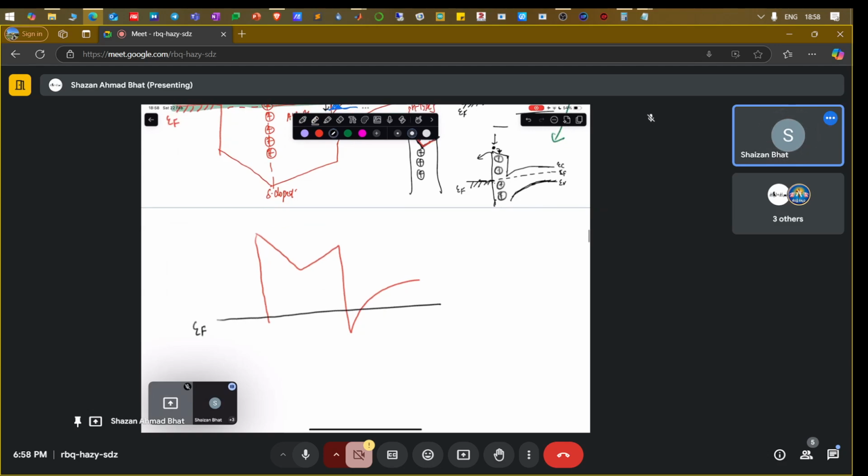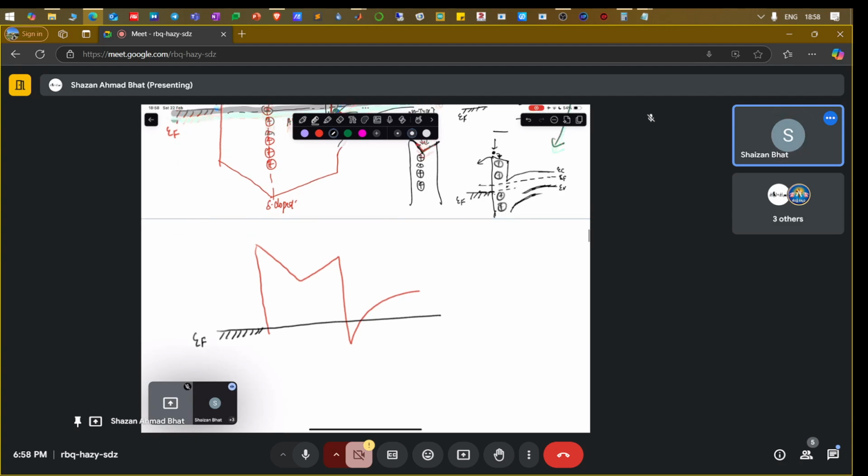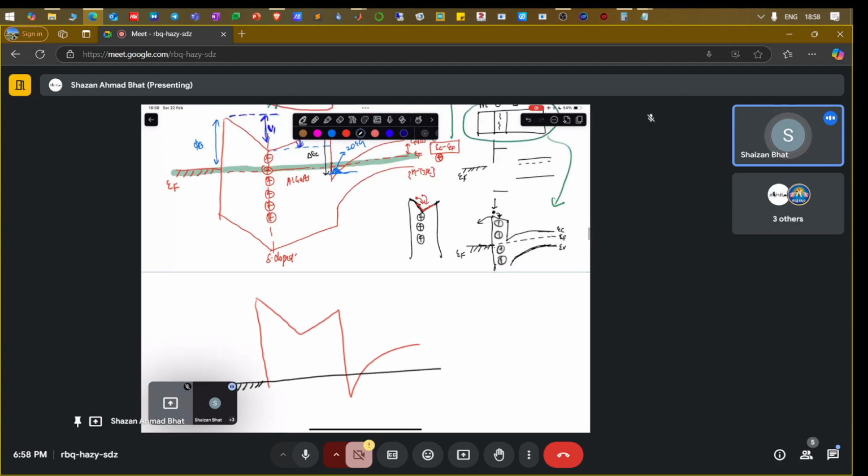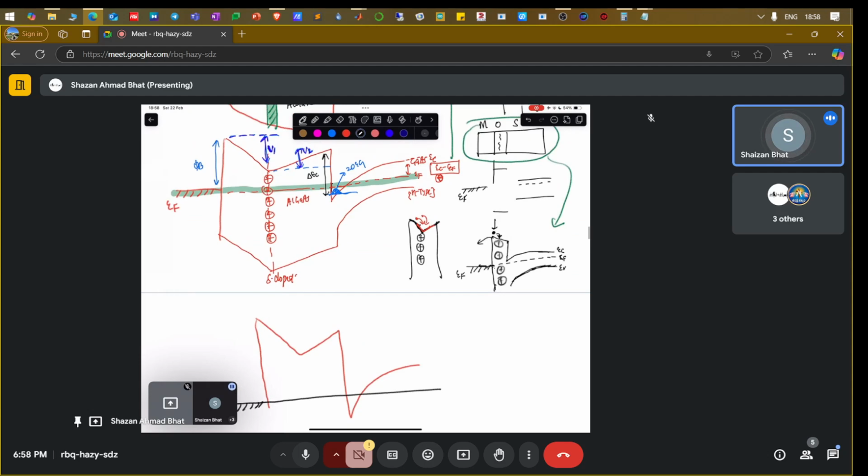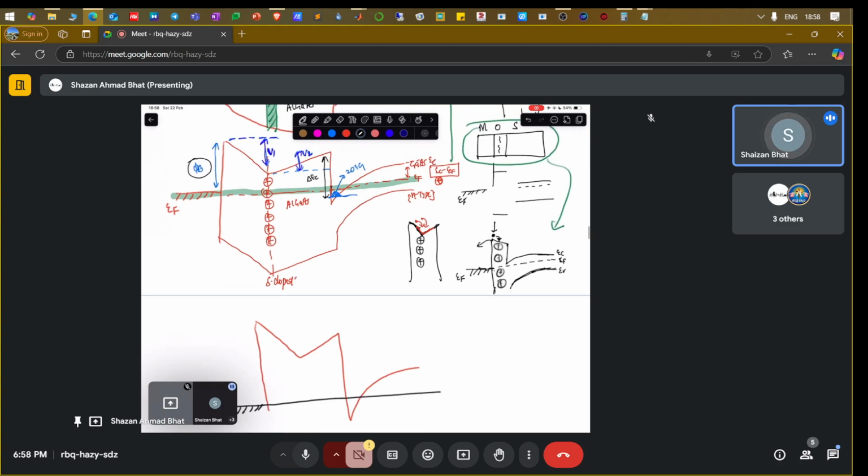This is the Fermi level on the metal side. Now you know these particular bendings: the Schottky barrier, which is phi b, V1, V2, the conduction band offset, and you also know this particular thing. Let's call this difference between the Fermi level and E0, which is the first eigenenergy of the two-dimensional electron gas, VDI, which is how much deeper the first eigenenergy is from the Fermi level.